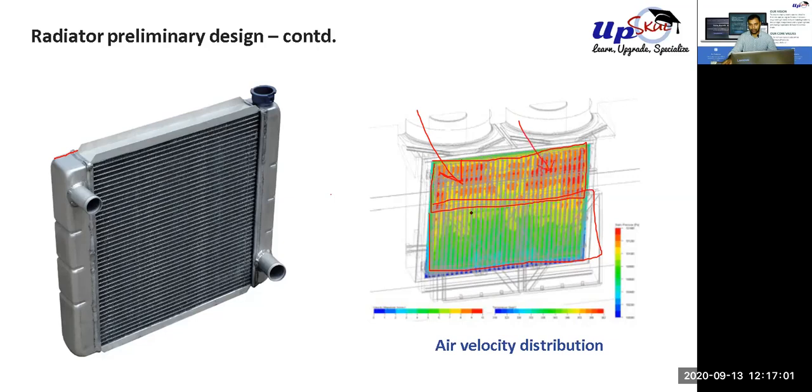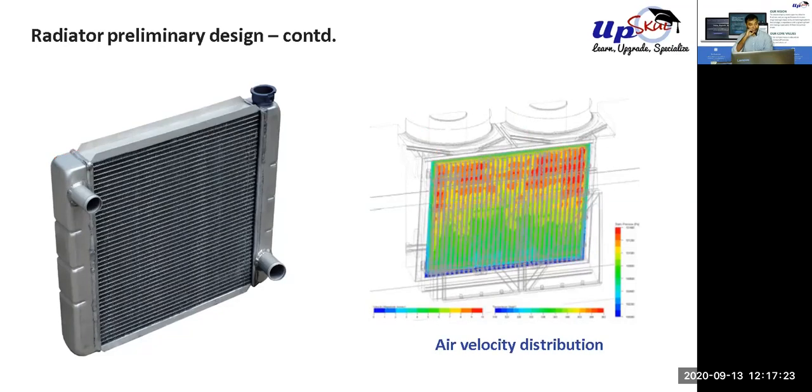If the fan was small and attached like this, all the air velocity would be in this area. There will be no air at the center of the fan because the center of the fan doesn't pull anything, because the motor is in the center. So all of this area would have been stagnant, only the area where the fan blades are would have had flow. So that's why fan calculation is important.